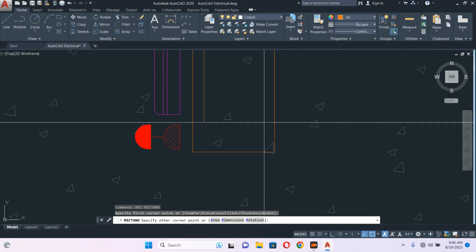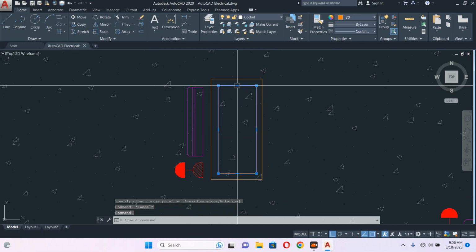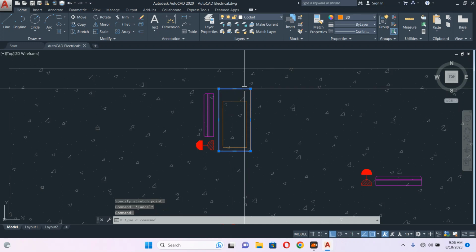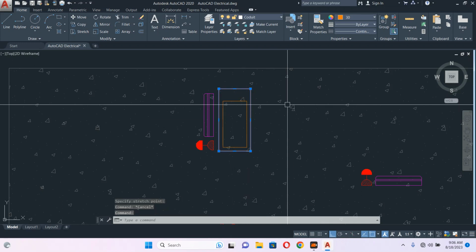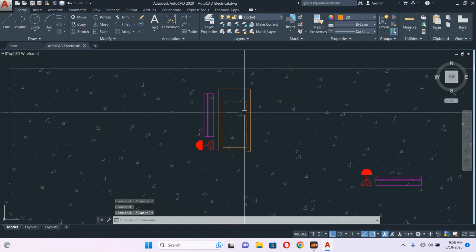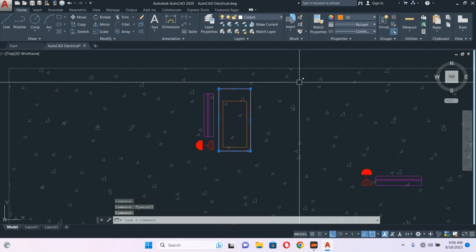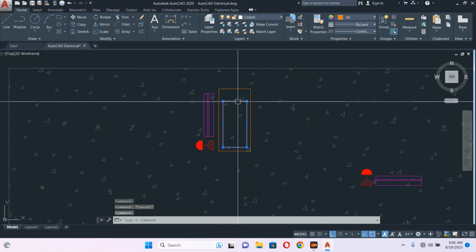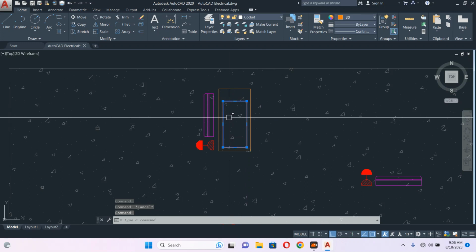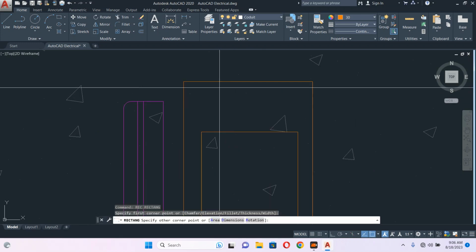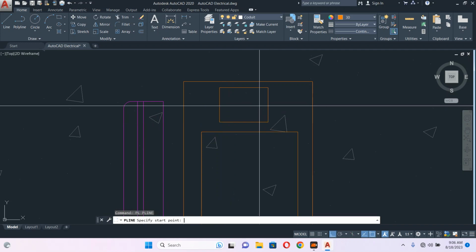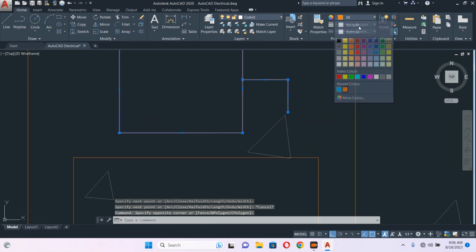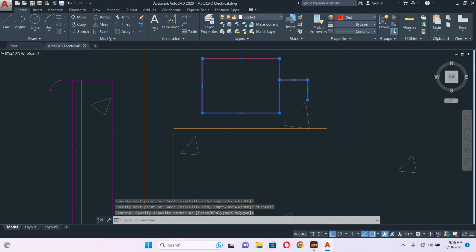It should be something like this, and this one should be a little inside. Why? This is for the concrete plinth, which is provided by the structural or architectural people. We call them the main contractor. They do all the structural and architecture, and we always become the subcontractor. So this one will be the outdoor unit, and there will be a tiny isolator here, a single piece. This isolator will be 20 ampere.